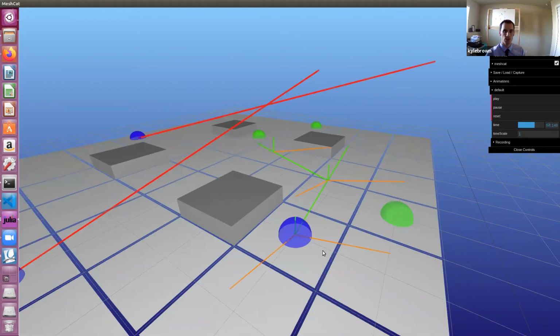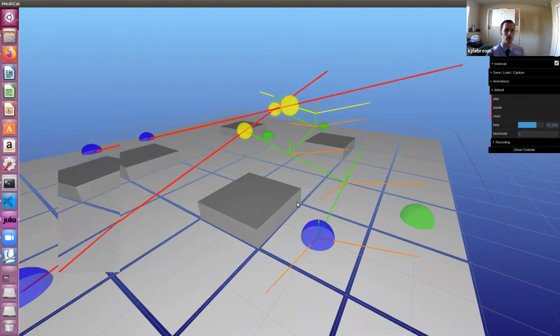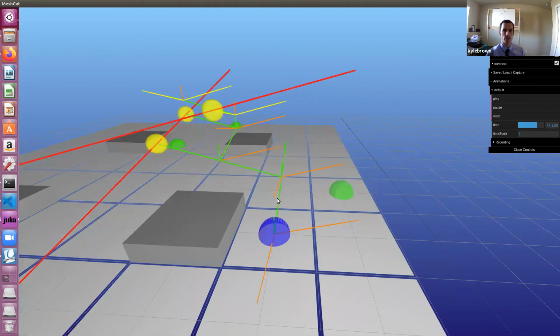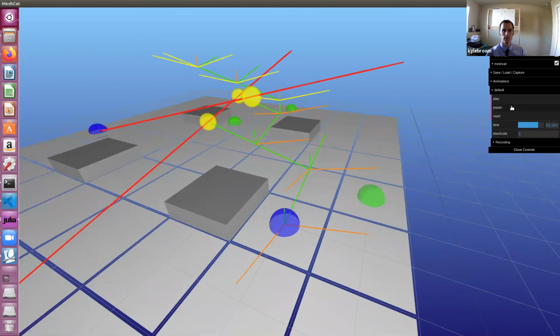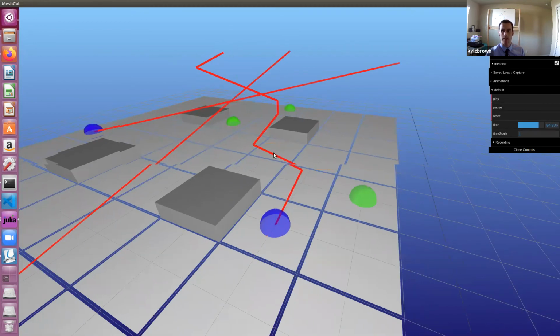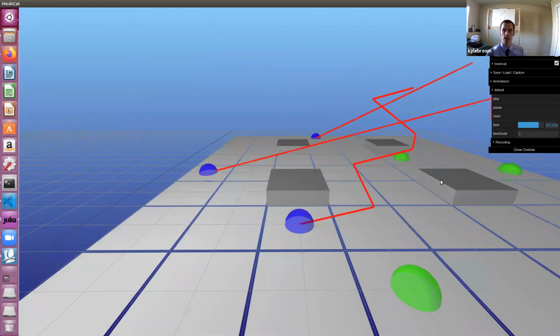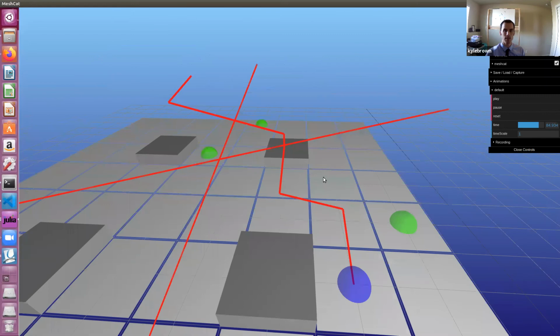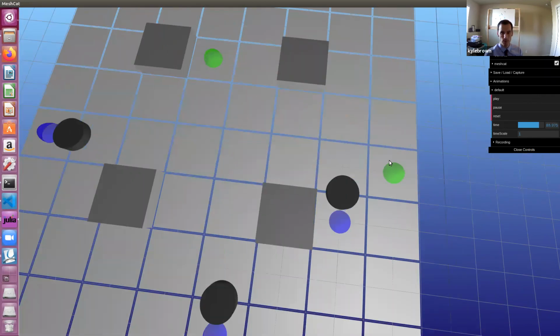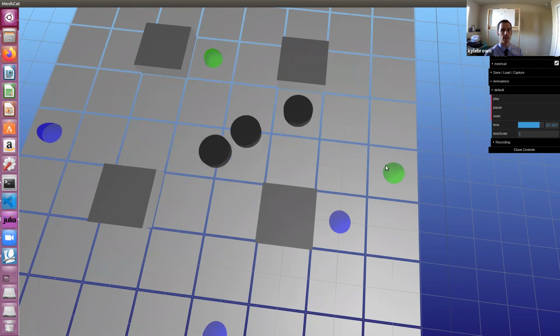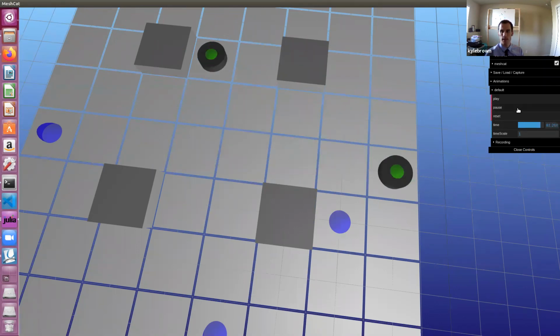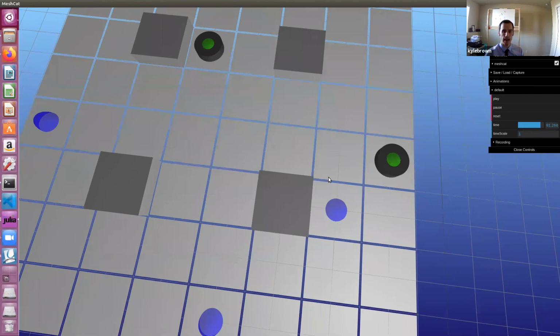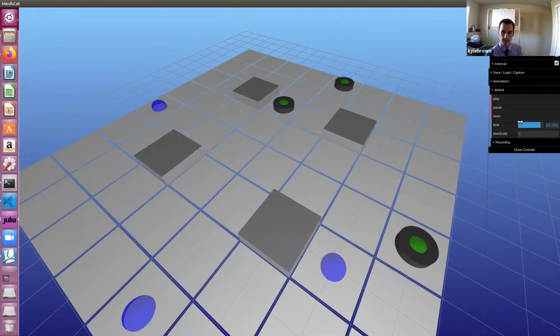So similar search procedure as before, we encounter a collision, and now you see the algorithm is trying out states that allow for a delay. And you'll see this clearly when the path is reconstructed. So there's the reconstructed path, and you can see there are no collisions with the other paths. If I play the animation of the robots actually moving along these paths, we have this happy result where we don't have any robots running into each other. Very exciting.